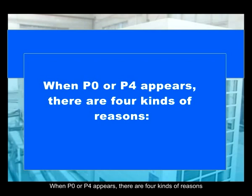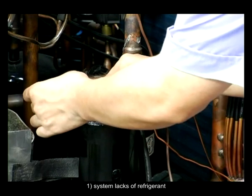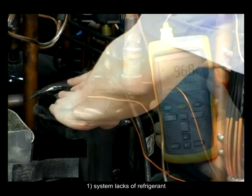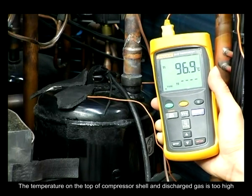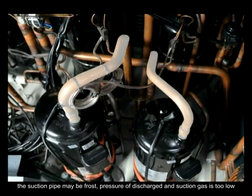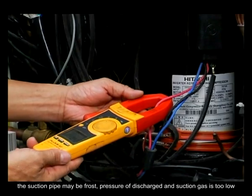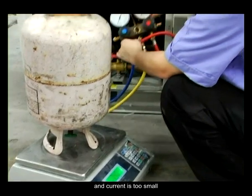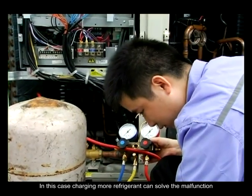When P0 or P4 appears, there are 4 kinds of reasons. One, system lacks refrigerant. The temperature on the top of compressor shell and discharged gas is too high. The suction pipe may be frosted. Pressure of discharged and suction gas is too low, and current is too small. In this case, charging more refrigerant can solve the malfunction.